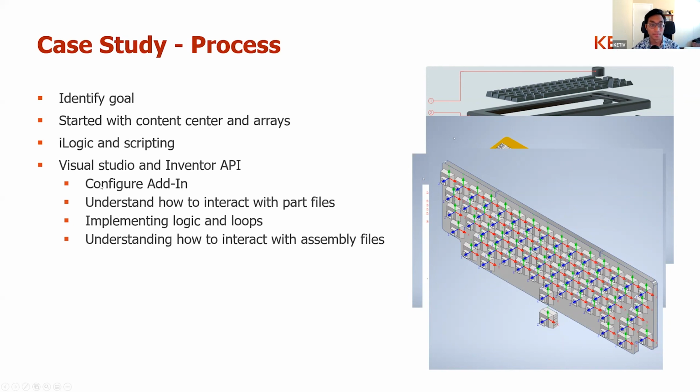And my process for that specifically, right? You obviously have to know how to do the add-in, which we have a video for as well. How do you interact with part files? Because it's still a bit different than what you'd be doing in iLogic, for example. Logic and loops are a bit more robust inside of Visual Studio, and understanding how to interact with assembly files also comes along with this as well.